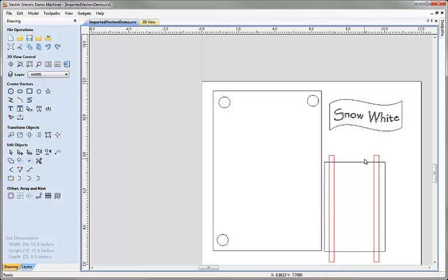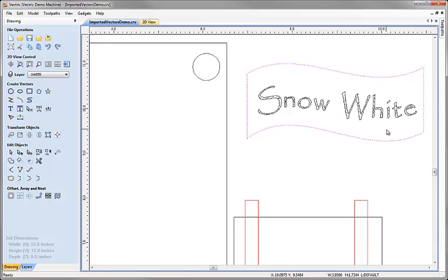Okay, the final thing I want to point out is that many file formats don't support the curves that we use, the Bezier curve type. In our software it would be trivial to draw a sweeping little curve like this using a single geometry segment, with the control handles that generate the curve in it. But in fact this has come from a DXF file, and the DXF file format does not support Bezier curves.